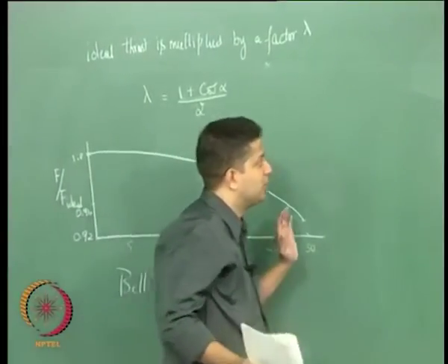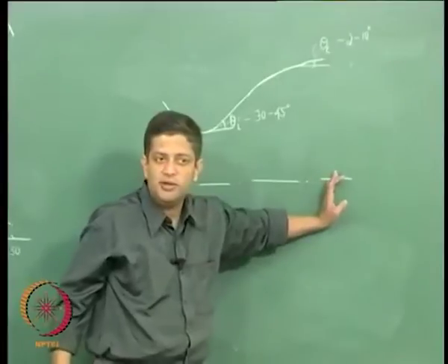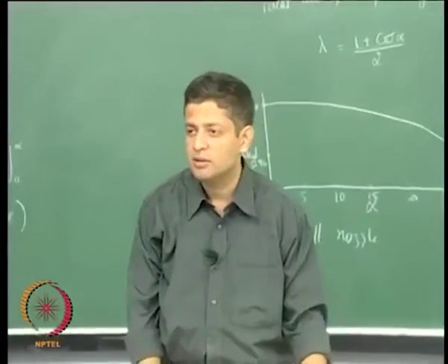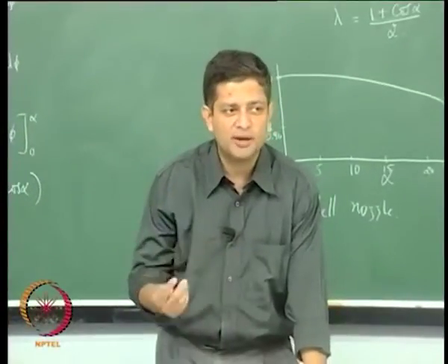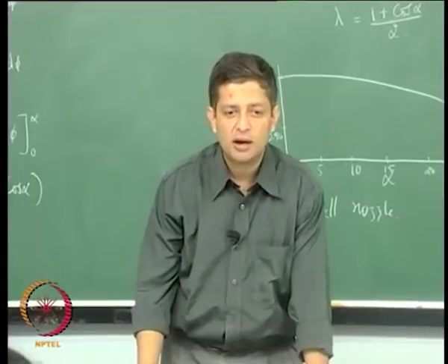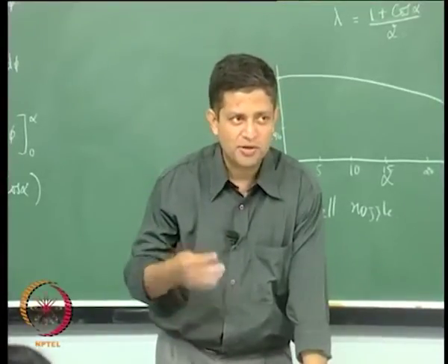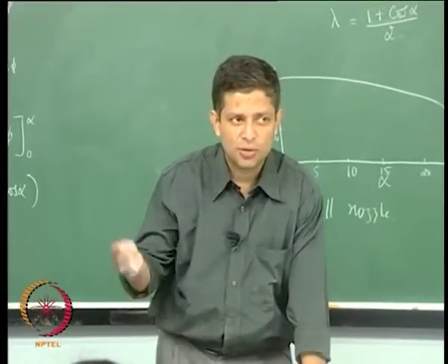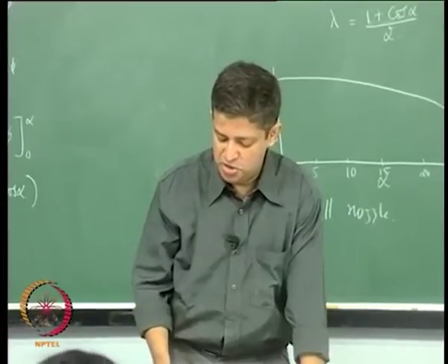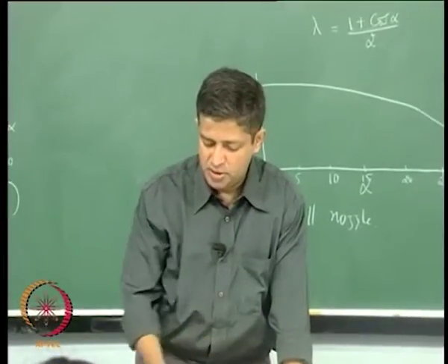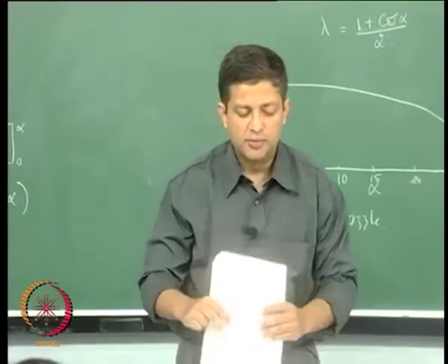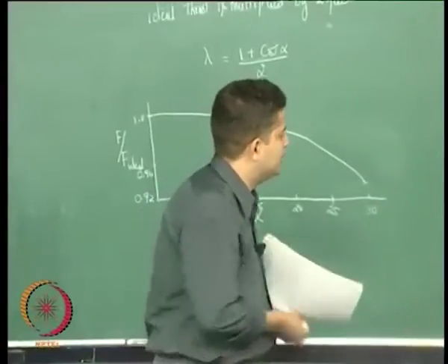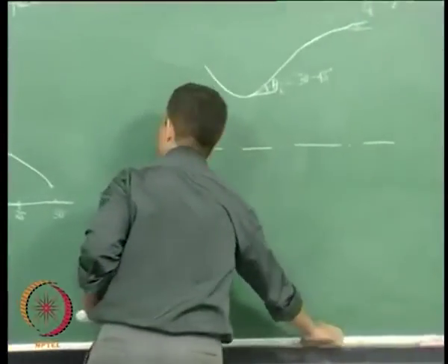Now, this would mean that you would have a shorter nozzle, therefore, the nozzle weight will be smaller, and also your cooling, remember nozzle is exposed to high temperature gases, your cooling load will also come down, because you will be having a smaller area wherein you need to cool the nozzle. Now, if you were to calculate what is the length saving that we will get, we can look at this table.